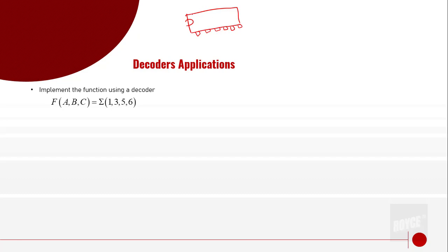Actually, dapat parang 7, no? Para 3 is to 8. So 1, 2, 3, 4, 5, 6, 7. So 3 inputs plus 8 outputs, so 11. Tapos meron syempre yan ground, 12. VCC niyan is 13. And then may isa yan na unused pin. So probably mga 14 pins na IC ito.